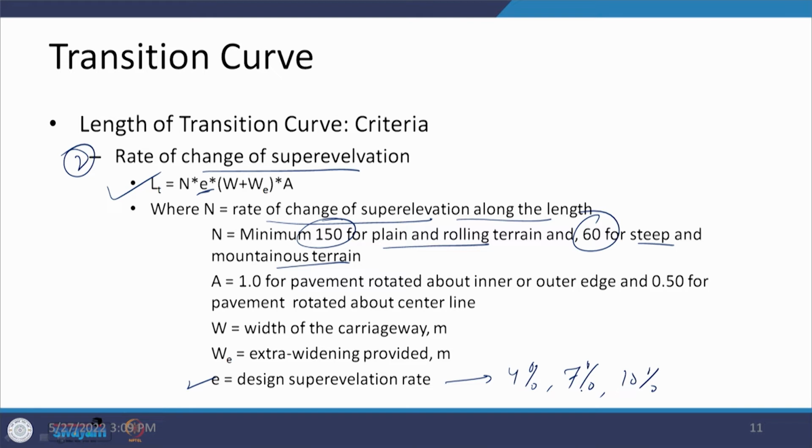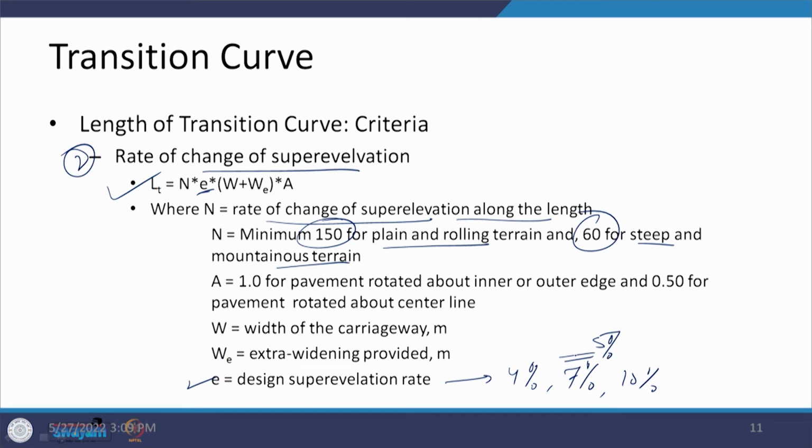And depending on whether the value of the radius is being provided in actual or is as per the design, whatever the values are there, the comparison of that also allows you to use a value of 5%. So, we had these values in hand. So, we can calculate, either we can design it or otherwise we can utilize the maximum values which can be possible, which is going to give you the maximum length for the transition curve for this particular vector.